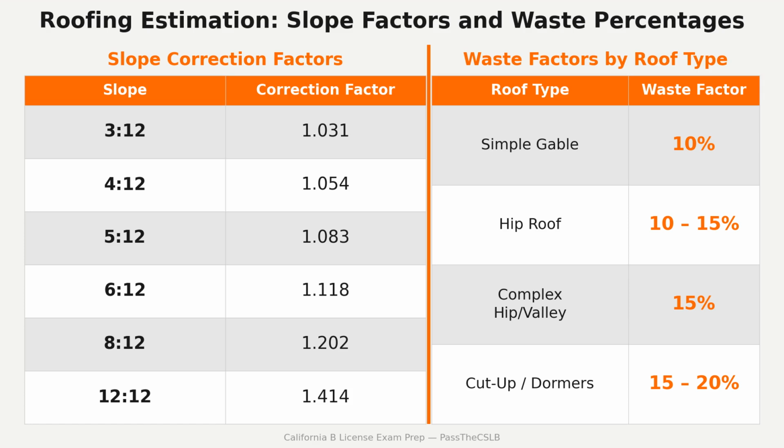Chimney flashing uses a 2-layer sliding system engineered specifically to accommodate differential movement between masonry and wood framing. A masonry chimney sinks with its foundation. A wood roof frame racks in seismic events and cycles thermally. Rigidly attaching a single flashing piece to both eventually tears it apart. The solution is a telescope. Picture 2 cylinders that overlap and slide independently of each other.